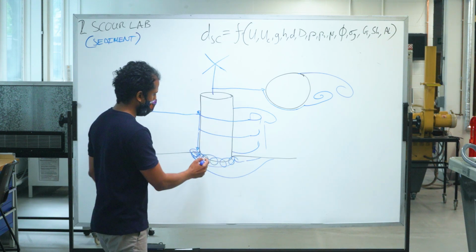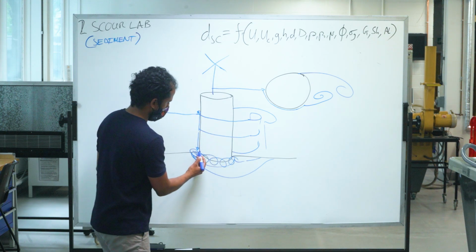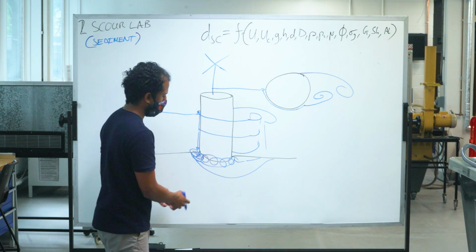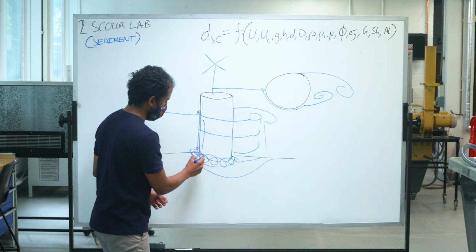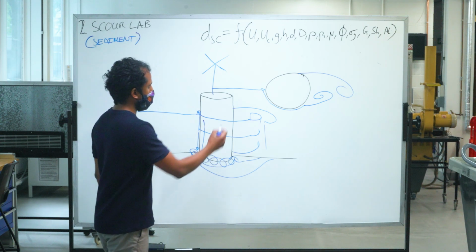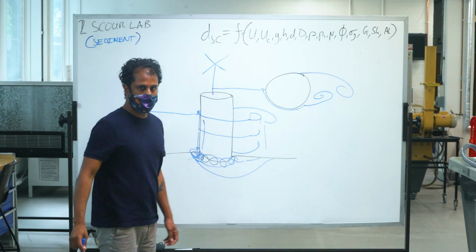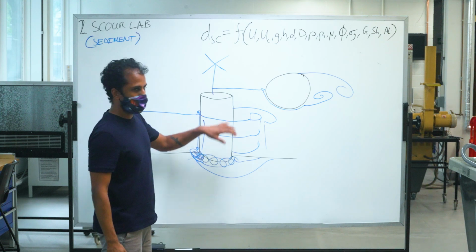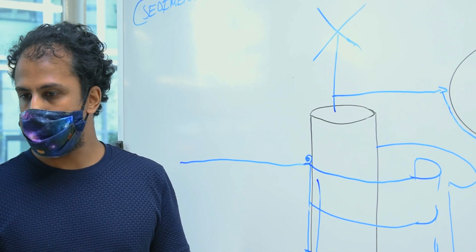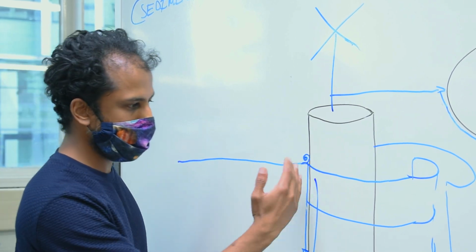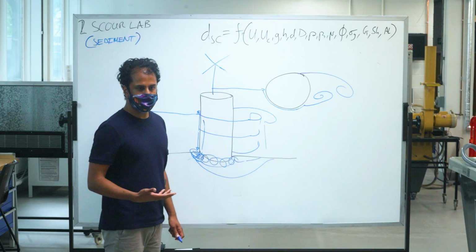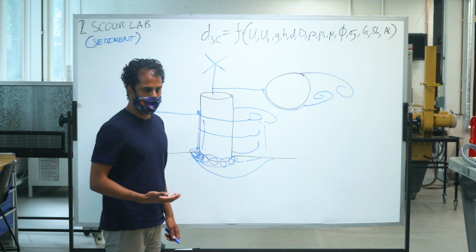So your bending moment is going to increase because the lever arm length is increasing because of this scour hole. Any cables which are attached to it might be exposed when they're not designed to be exposed. It might change the vibration behavior of the whole structure if it's got a wind turbine on top, and so on. You might even induce vortex-induced vibrations of the whole structure as well. So it's a very important thing to be aware of.